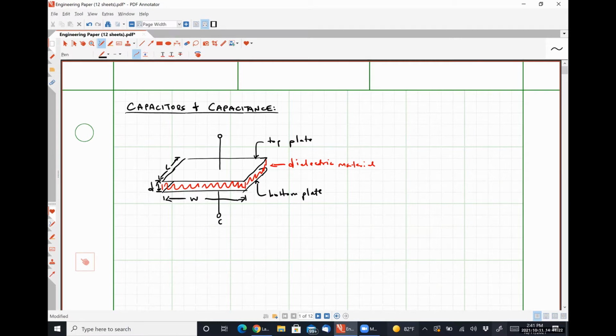Now, when I walked in the room, there was a question about what capacitors are made of. Capacitance occurs anytime there are two conductive materials near each other that don't have a conductive path between them. Full stop, okay? Doesn't matter if it's two chunks of semiconductor material or metal plates or some combination thereof. If it is two conductors next to each other, so even a pair of wires that aren't connected exhibit some capacitance, but it'll typically be pretty small because the area of overlap between those two conductors is small, okay?